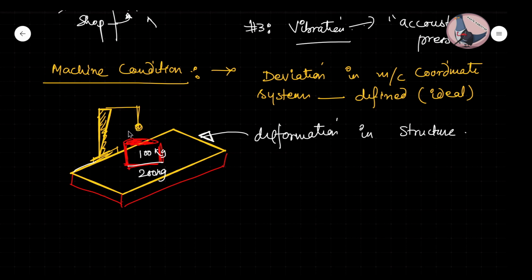Okay, or if you are using this machine for years, and due to the weight of this entire probing system, if this thing just slants a little bit, then also you can understand there will be some error. Now, of course, this deviation you cannot see very apparently, and this error will just be seeping into your measurements.